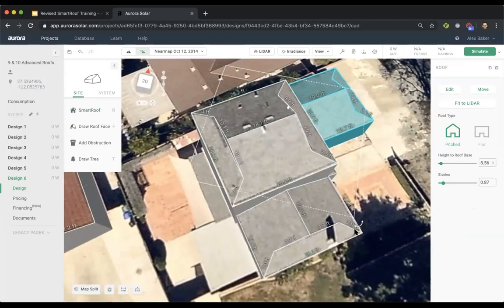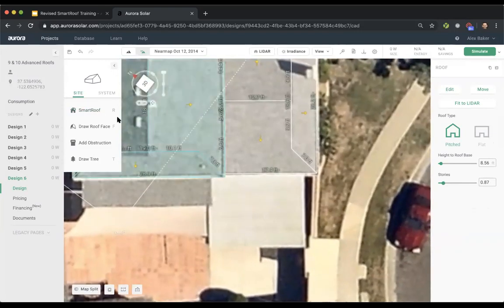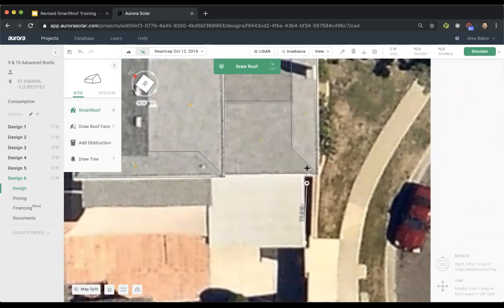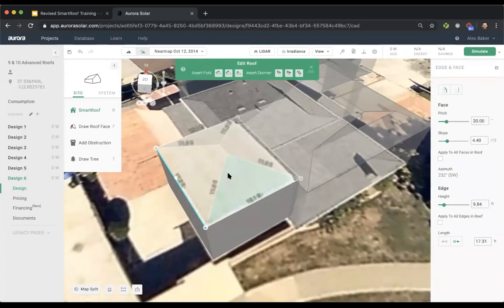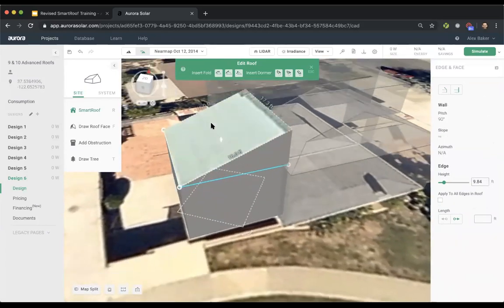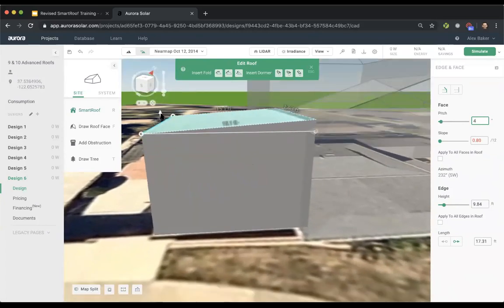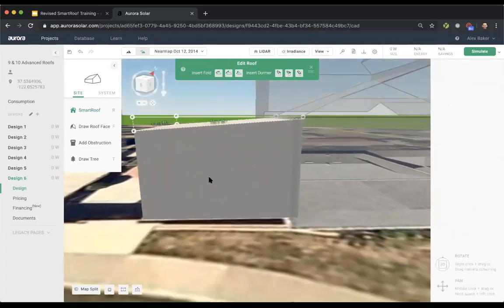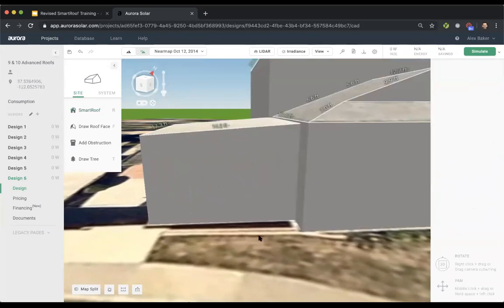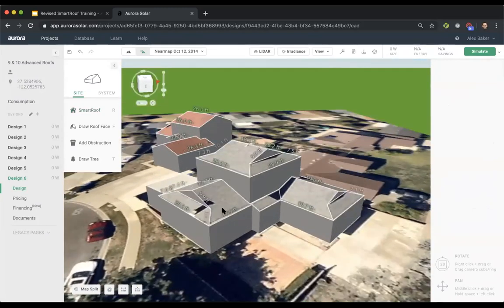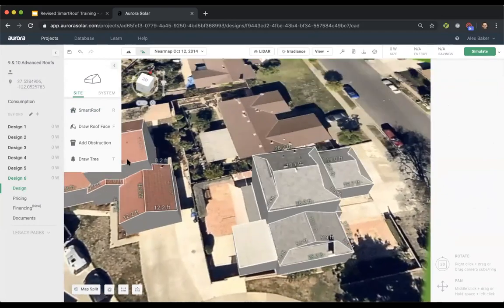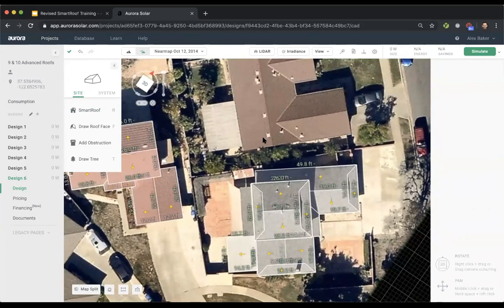All right, perfect. So the last piece I want to do today is this little extension. This is pretty simple. I just want to overlap this a little bit. And then I only want to keep one slope. So I'm going to just select these 3, unpitch those, and then I'm going to decrease my pitch significantly. And then I just want to lower the eave line so this roof is below. If I double click, these all automatically merge. And there we have our last advanced roof of the day. So I'll save that. Now that concludes our final design of the day.